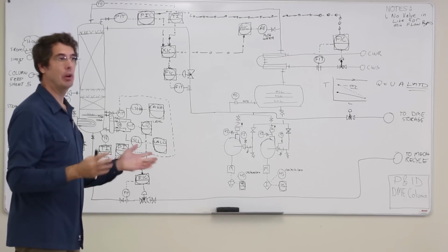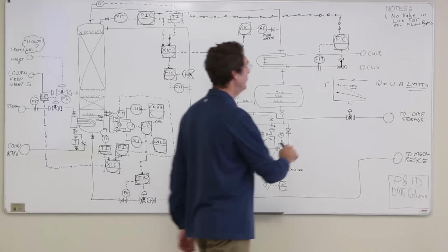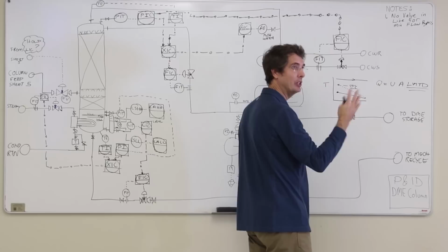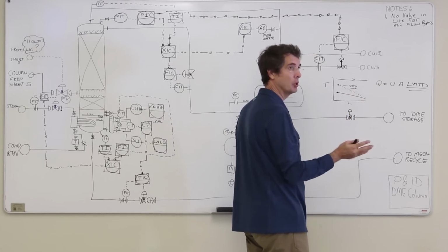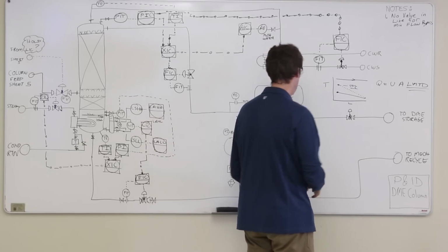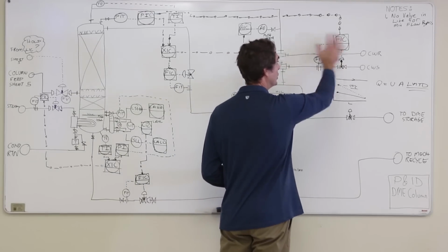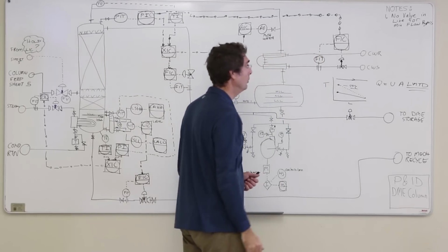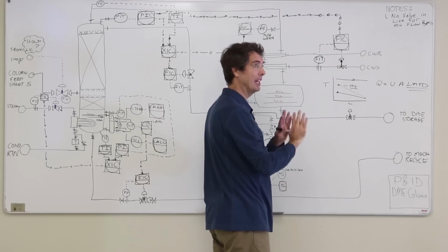Yeah, and we don't really want to return it back all that hot as well. So we've designed it for like 45 degrees Celsius, and if it starts to swing up, you'll hit 50, 60 degrees Celsius potentially, and that's going to cause stress corrosion cracking. It's going to send the water back a little bit too hot. So one of the recommendations for this cooling water control system is to pick up the temperature on the outlet of the cooling water and control the inlet flow rate so that you hold it at 50 degrees Celsius. Just let the cooling water rip.